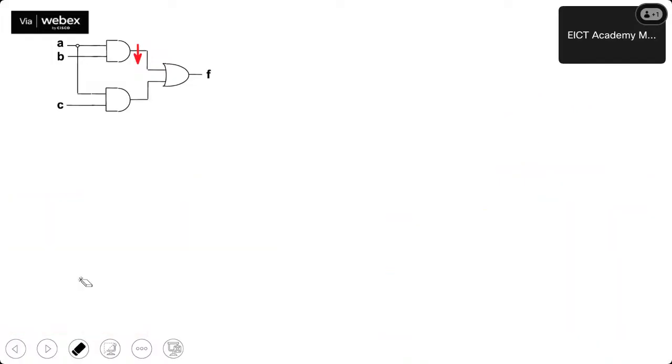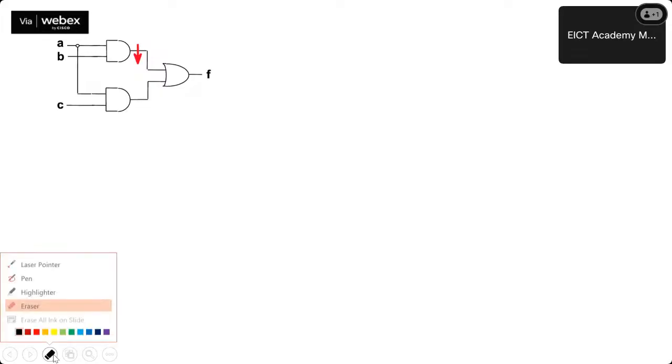that instead of the fault at site A, let us have the fault over here. This is the fault, and in order to deal with this, how to start? So look, this fault is there, not at the inputs. If it is not at the inputs, first of all, make sure that you give a name to each and every gate and each and every branch. So give a name to all of these. Let's say this is G1, G2, G3, like that. And let's say this is H, this is I. Okay, any name you can give.